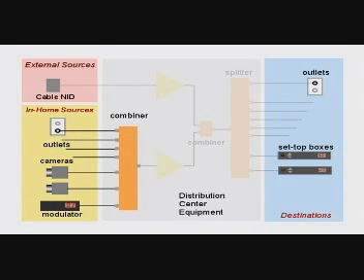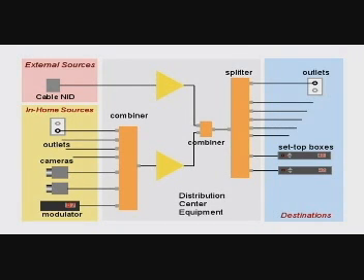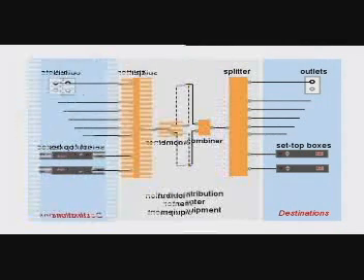All internal coax runs are combined into a single internal source that contains all the modulated channels. Depending on the number of inputs, the combined signal may need to be amplified. The external source is also amplified, and the external and internal signals are combined. The result is then split as necessary to support all the external cable runs. Almost all residential distribution systems will be some variation of this design.